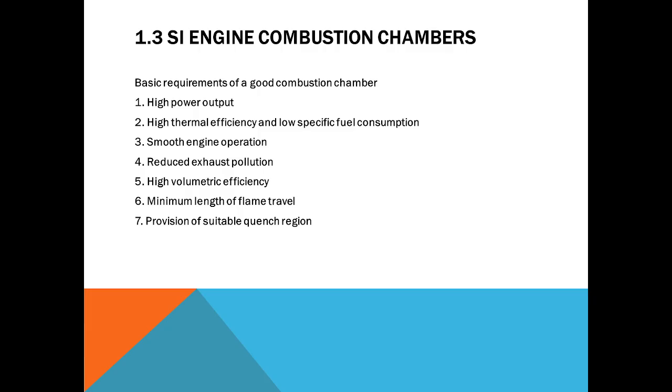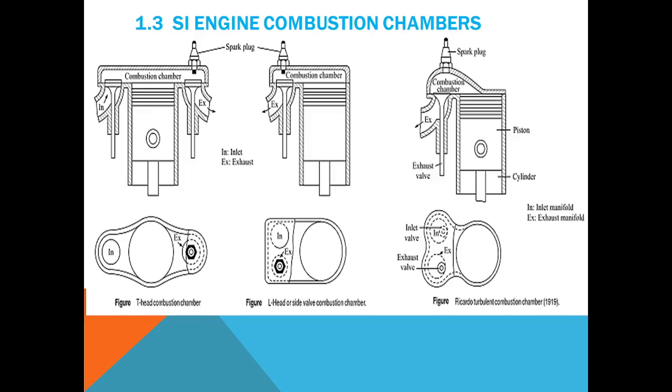A combustion chamber should give high power output and high thermal efficiency with low specific fuel consumption. The engine operation should be smoother. It should give less exhaust emissions to reduce the pollution. High volumetric efficiency, minimum length of flame travel, and provision of a suitable quench region are some of the good qualities of the combustion chamber.